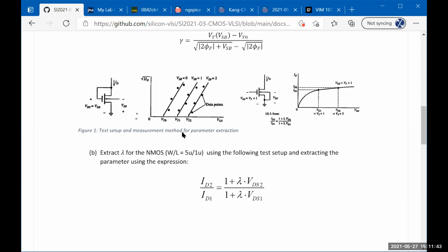Some of the parameters they will extract indirectly, like the doping. Let's say they're trying to do the doping 10 to the power 14 per centimeter cube. That's their intention. But after the doping is done, it's something else because of all the imperfections in their tools. So they have to extract even that doping through measurements by doing sheet rho and stuff like that. Like you would have seen yesterday, we calculated the sheet rho of aluminum, but when we went to the document which uses aluminum, the sheet rho is different. And those differences are what you use the measurement to capture.